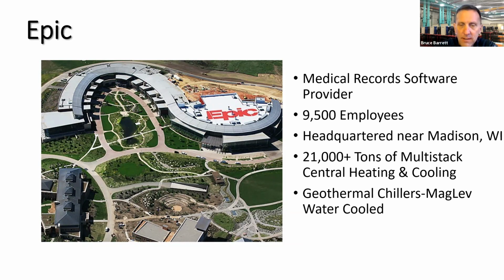You're absolutely invited to come up to our plant. We can stop in Madison, Verona area along the way. They're very proud to do plant tours. It's mind-blowing. It's like Disneyland. They incorporate not only geothermal chillers, but a lot of mag-bearing chillers operating off the condenser water loop of the geofield. Extremely efficient, something like a 0.42 kW per ton plant efficiency. Pumps, chillers included, super efficient.